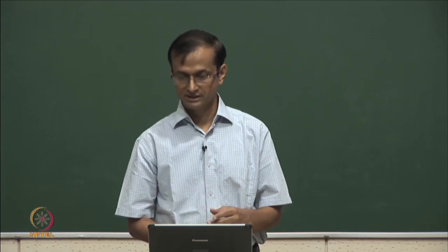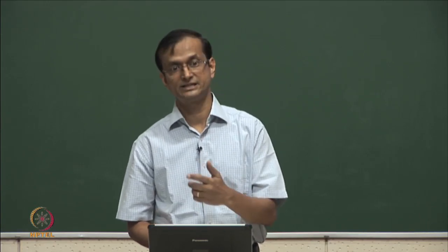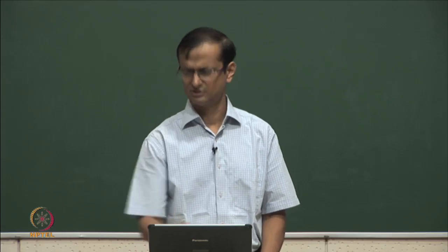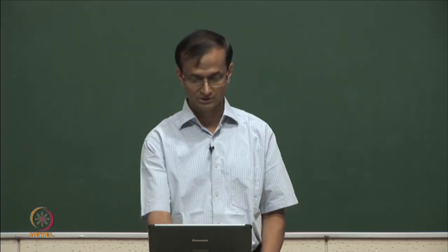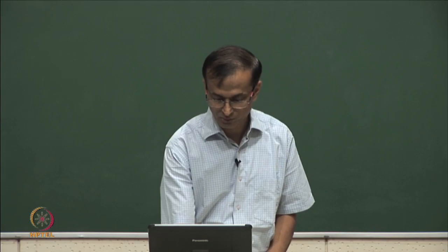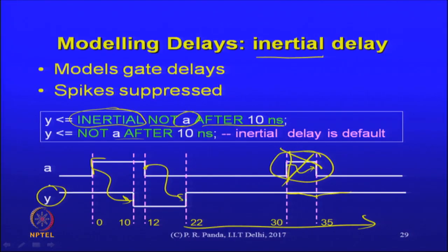Right. So, it is not as though it begins to fall and then gets back, because then it is not a purely digital simulation, it is not a 0-1 simulation. Remember, what is the type for y? We declared the type in our design. It was a bit type, right. That bit type is forced by the language to carry only 0 and 1 values, right. So, the opportunity for me to show a wave falling and rising in the intermediate levels between 0 and 1 does not exist, at least for that type it does not exist.